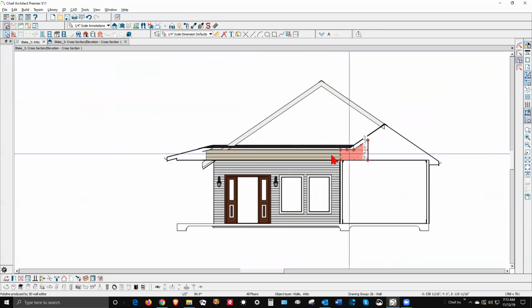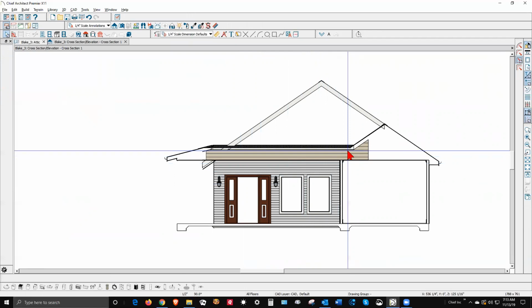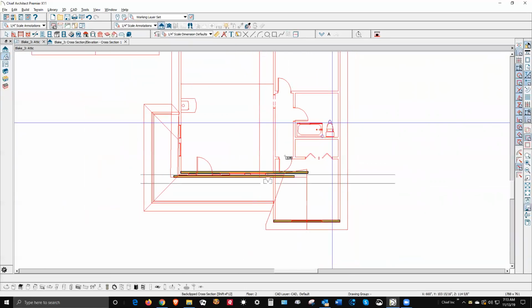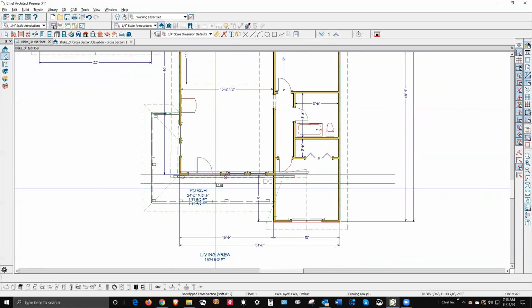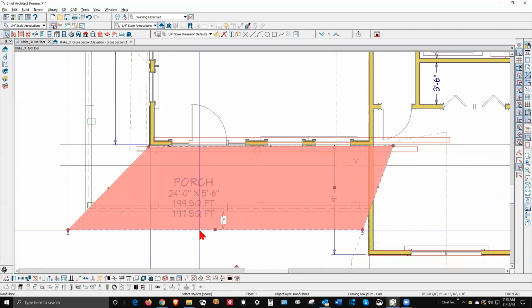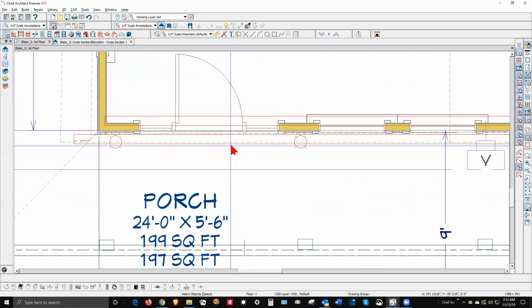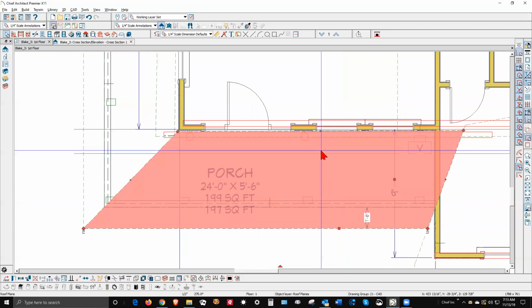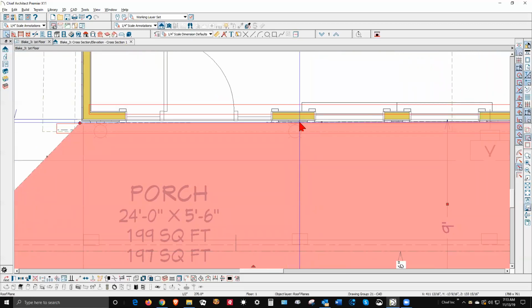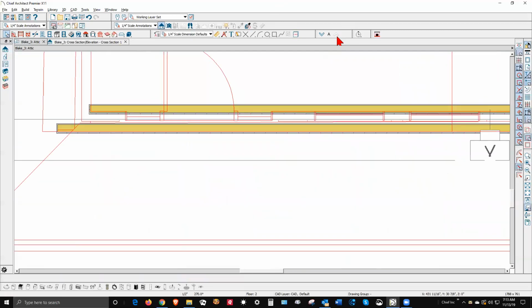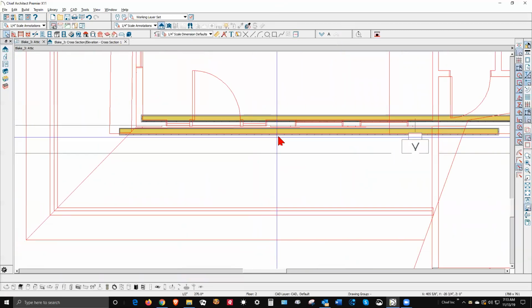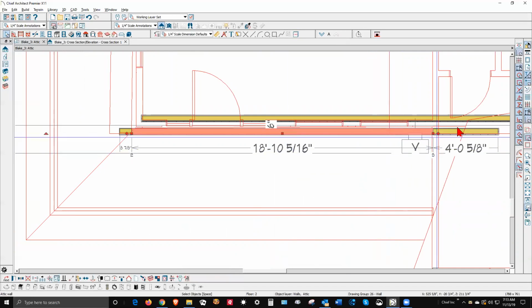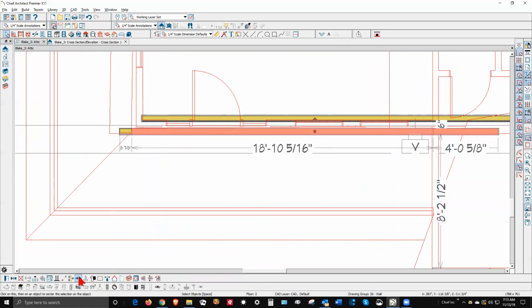Okay. So that wall that I drew is underneath the edge of the, yeah, okay, I see what's happening. I've done this before, so it's not all that mysterious to me. A new person, that wall I drew is up here, and it's out of alignment with this wall here. And I've got the edge of the roof plane, but that's the upper one. Here's the lower one. See, it's just shy of this wall here. And roof planes, excuse me, are pre-programmed to be cut off by roof planes.